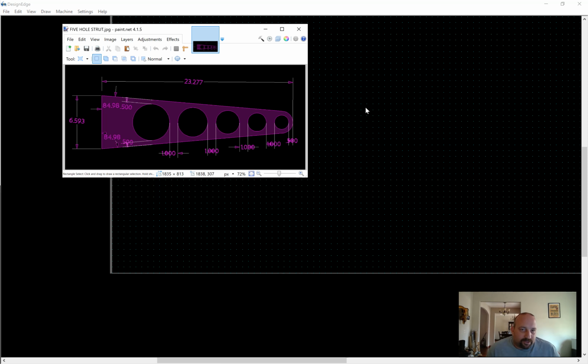It all comes down to drawing a circle that is tangential to two different line segments. So we're kind of back in fuddling about in geometry because you have to bisect an angle to get it accurate. You cannot use the orthogonal snap unless the lines are parallel, because you'd be bisecting a 90-degree angle if they were parallel, but they are not parallel in this example.